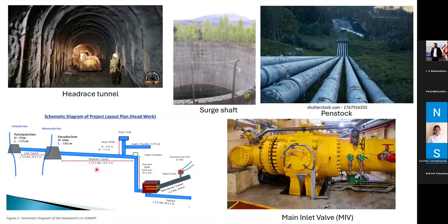The length is 15.2 kilometers and the drop is only 4.3 meters throughout the whole 15.2 kilometers. Even the linking tunnel, a 3.9 kilometer long tunnel, has a 4.5 meter drop. It's a very small slope in those two tunnels to avoid hydraulic damage to the tunnel.